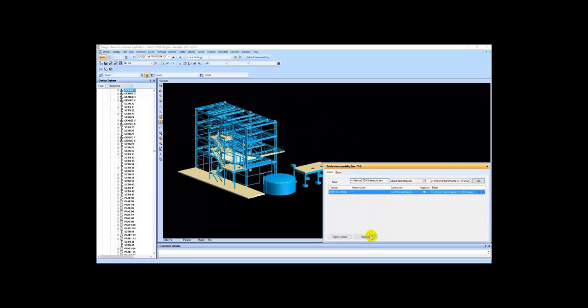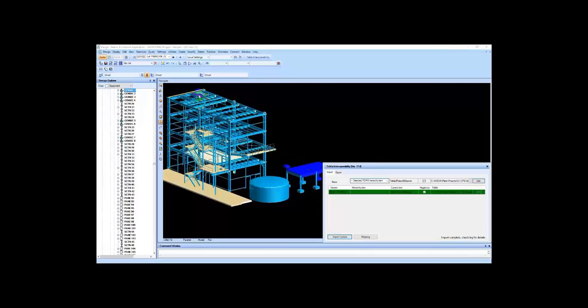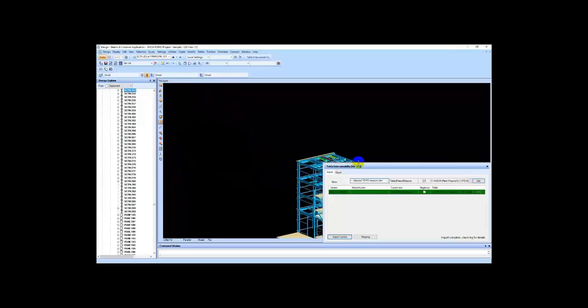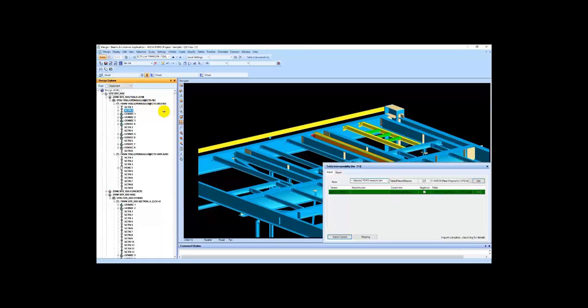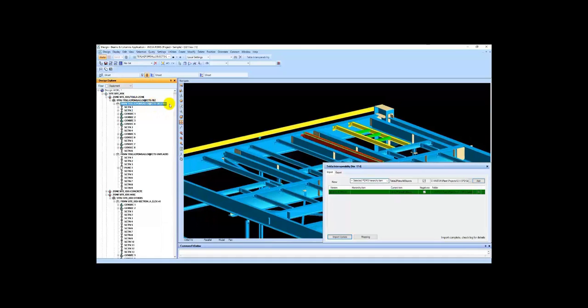If a new updated export file from Tekla exists, then a yellow row color appears in the dialog, and pressing the import update button, the updated situation will be imported to PDMS. Different colors show status in PDMS. Green is for new objects, yellow for modified, where the PDMS ID number remains, and so, for example, linked drawings remain.